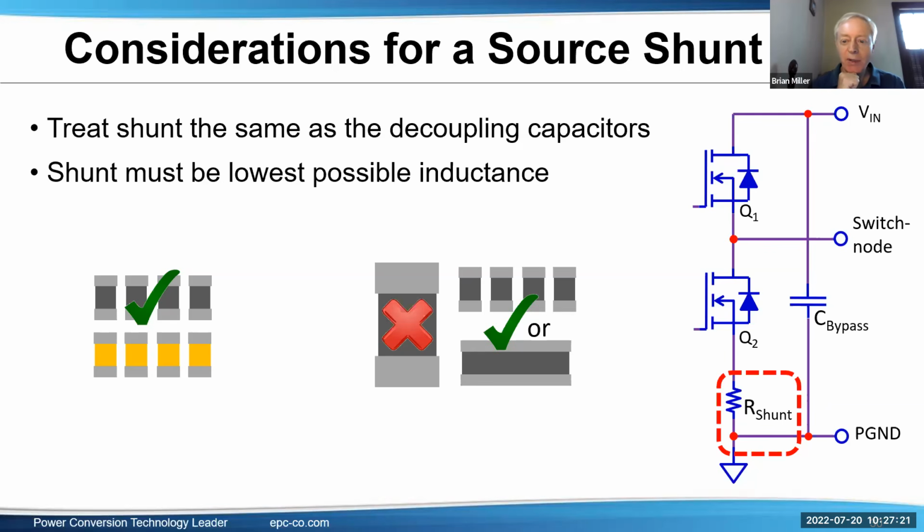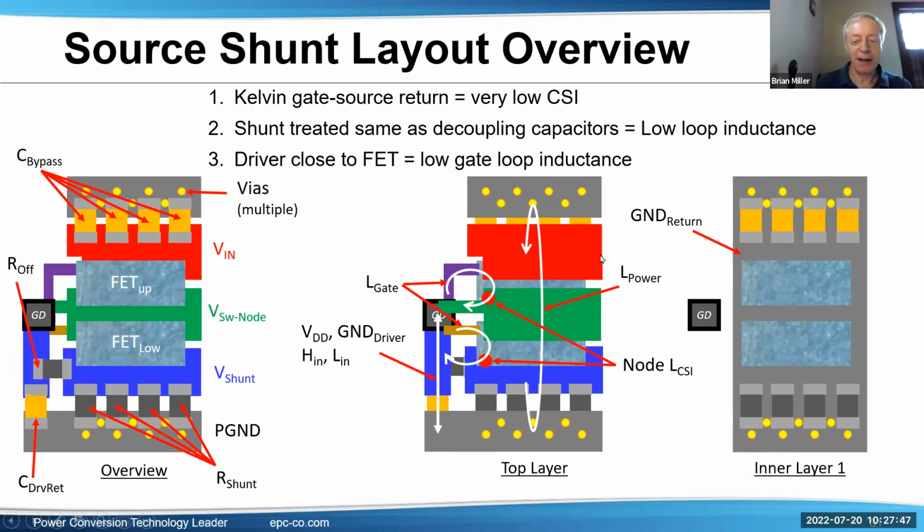I should add here, there's at least two GaN gate drivers that allow you to separate the resistive shunt out of the lower gate drive loop, which is nice. One from onsemi, one from ST. So those are something that could be worth considering also if you'd really rather not have those in the gate loop. First shunt layout. This is very similar to the one we just showed, where capacitors, top FET, bottom FET. In this case, here's the current sense resistors down here, and then going to the ground. So same general concept, just added resistors here.